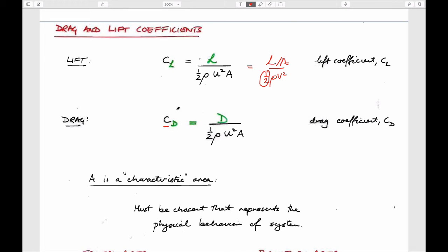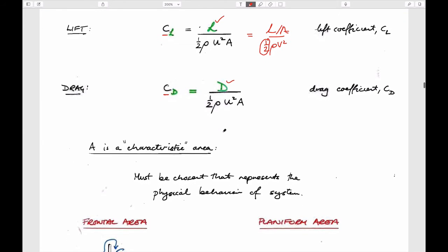If we know what these magnitudes are from tabulations, and we know what the velocities of flow are, then typically we can calculate what the lift or drag forces are which are applied on our structure. So it's actually the same problem as solving for flow in a pipe, where you have a friction factor, but here we have a coefficient of drag, and we have this transition between laminar and turbulent.